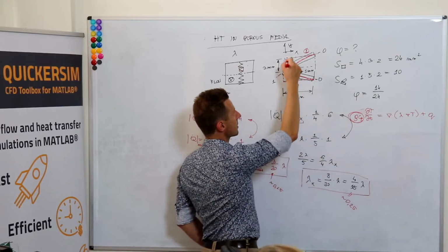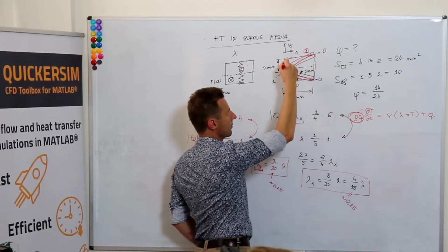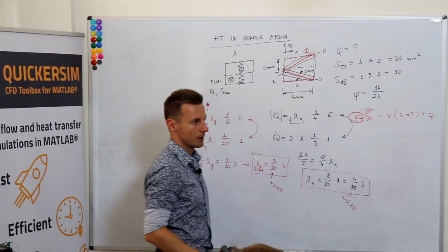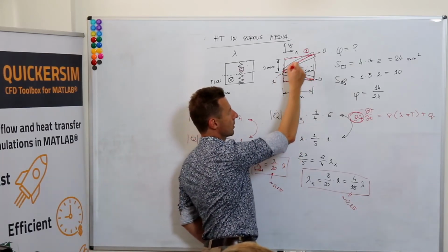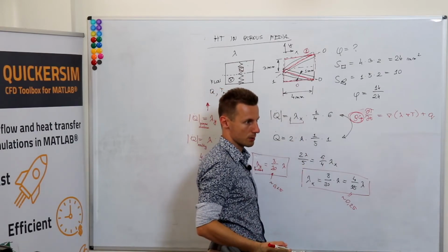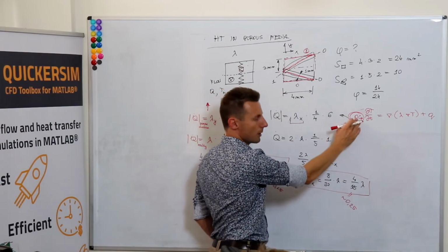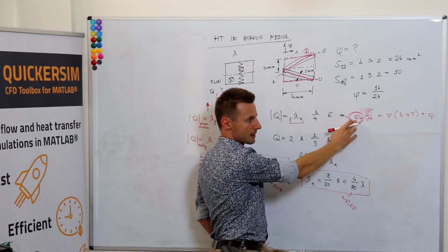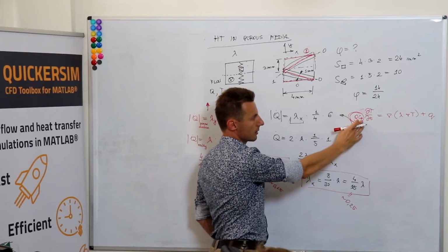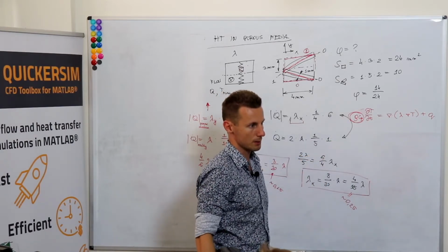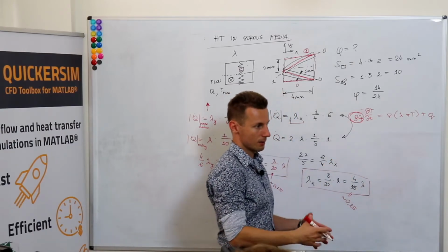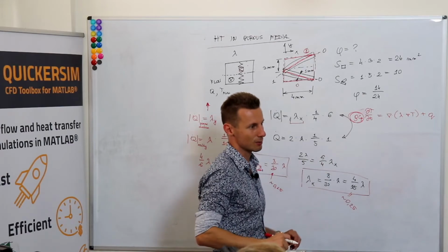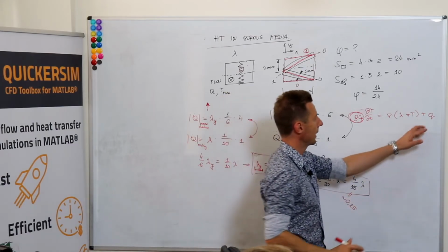So to say that your representative element of the porous medium has got the same mass as your metal sheet that is enclosed within it. So you would be lowering the density. But if you do that, then CP should stay the same, because you still have got this material that is less dense in your simulation, so to say.